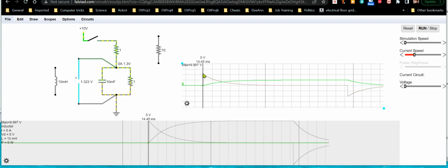It'll never be as high, like in this example, as this 10 amps ever again, until you change the state of the switch. It's never going to be more than 10 amps. It's a decreasing current. And the same here, when you flip it over to discharge phase, it'll continuously decrease towards 0, from a negative value, until it's fully discharged.